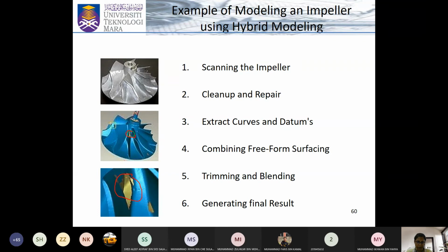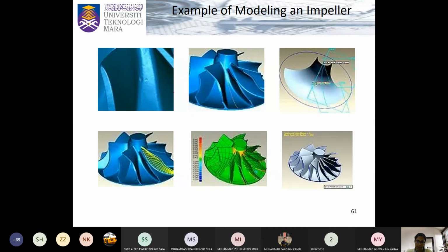In this area, what you do is trace this boundary out and patch this boundary, that means make a surface form. Once the surface is formed, then you extrude the surface. You would have realized by now in CATIA, when you are extruding a solid into a solid, it merges, so it doesn't matter. That's the same thing we're going to do: extrude a solid into a solid. So it merges, and then you trim off and you'll get a smooth surface.